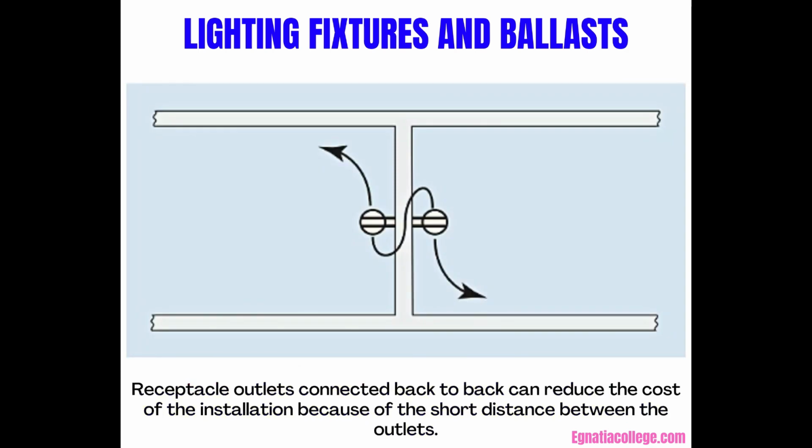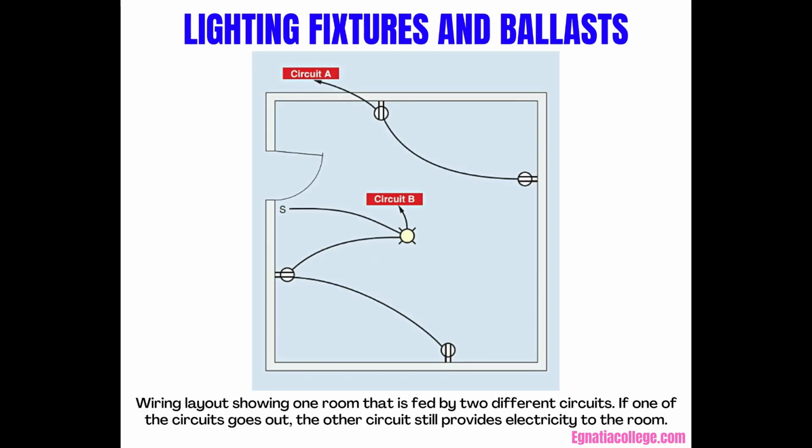An electrician plans circuits that are economical without sacrificing the quality of the installation. For example, some electricians prefer to have more than one circuit feed a room. Should one circuit have a problem, the second circuit would still supply power to the other outlets in that room. Some electricians consider it poor practice to include outlets on different floors on the same circuit. Here, too, the decision can be a matter of personal choice. Some local building codes limit this type of installation to lights at the head and foot of a stairway.